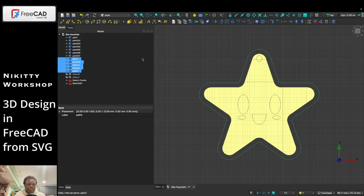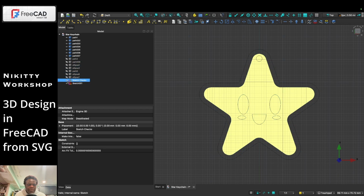So see, it created sketch 001. This is highlighted already, so I'm gonna hit the space bar to put them to sleep. So here, I'm gonna put that to sleep. You could click on the eye as well, and it puts it to sleep. So this is a sketch.